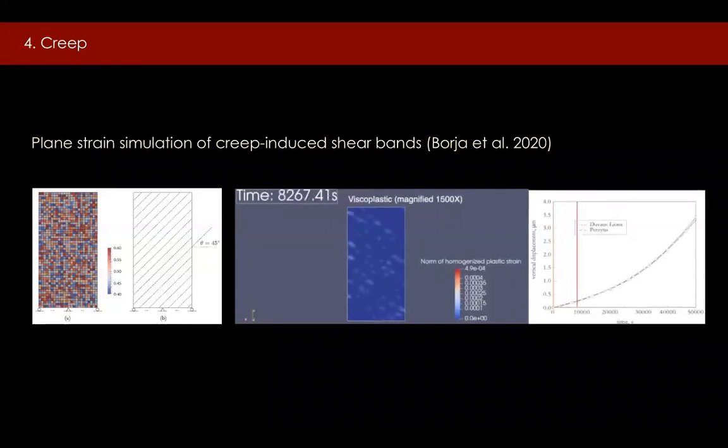The video shows an interesting pattern in which shear bands are generally oriented in the weaker bed normal direction, but smaller shear bands are arranged in phalanx formation, aligned with the bedding plane. Note that if there was no anisotropy, the shear bands would be randomly positioned and randomly oriented, but not in this example where the material is transversely isotropic. To my knowledge, this is the first time that shear bands are shown to be numerically reproduced under the condition of a constant load.